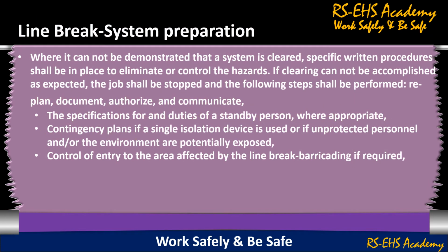Line break system preparation. Where it cannot be demonstrated that a system is cleared, a specific written procedure shall be in place to eliminate or control the hazards. If cleaning cannot be accomplished as expected, the job shall be stopped and the following steps shall be performed. Replan, document, authorize and communicate the specifications for and duties of a standby person where appropriate. Contingency plans if a single isolation device is used or if unprotected personnel and or the environment are potentially exposed. Control of entry to the area affected by the line break, barricading if required.